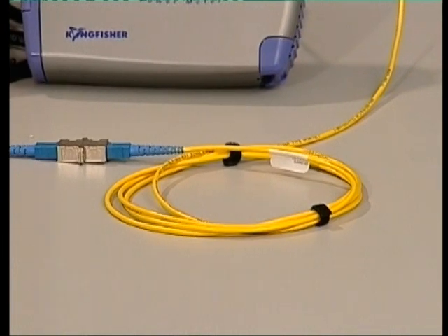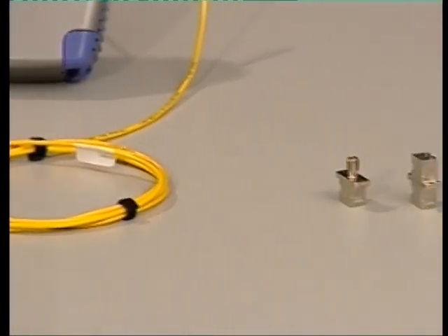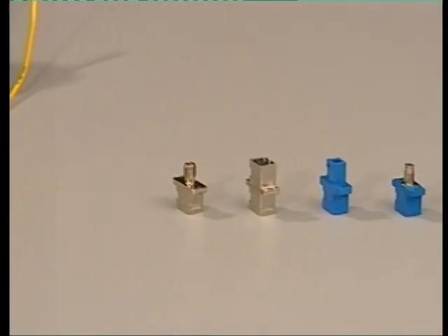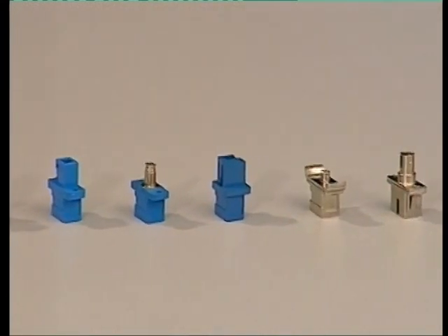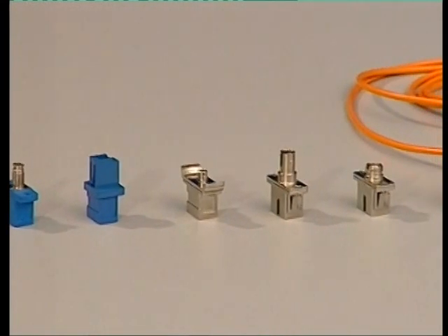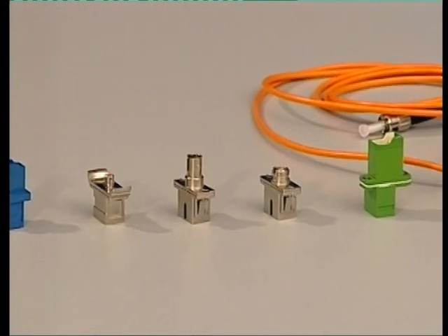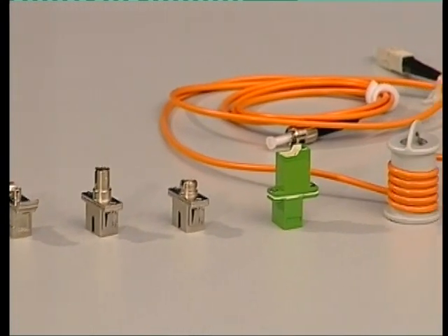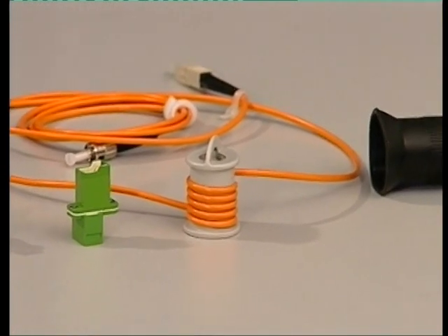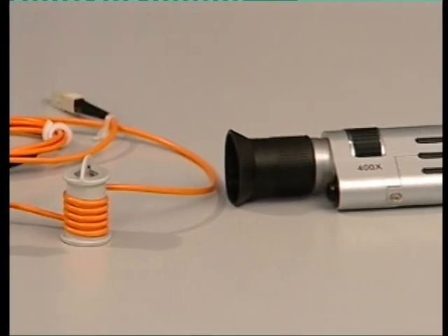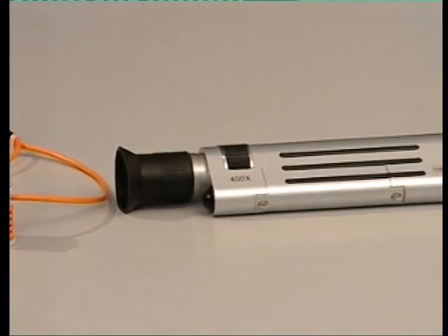Ceramic connectors have a lifetime of about 1,000 insertions due to mechanical wear. So in a test environment, test leads and through connectors require a management program so that they are regularly replaced. In use, connector ends must be regularly inspected with a good quality microscope. So each test operator needs a microscope.